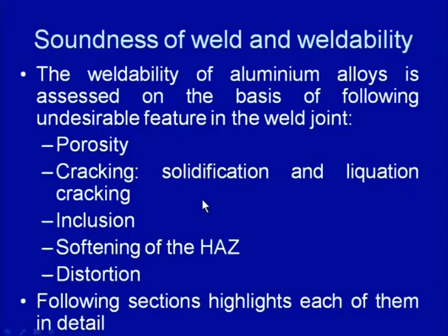So, melting is not required, and because of this avoidance of melting, the weld joints which are produced by the friction stir welding process of the aluminum alloys are found to be of very good quality, and a lot of research is still being done on the weldability of the aluminum alloys using the friction stir welding process.